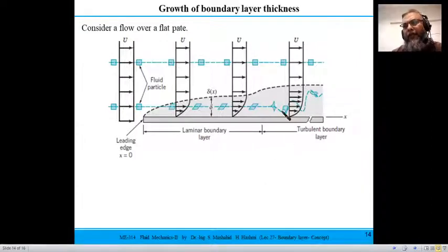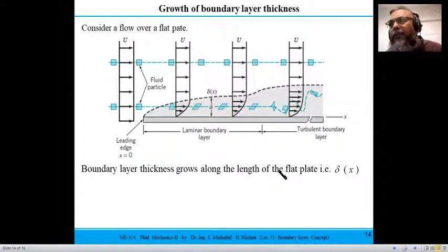And then there is a transition, and then the flow becomes turbulent. So velocity changes take place inside the boundary layer, and in the region outside the boundary layer, no velocity changes take place. So the fluid particle is experiencing no distortion. That would be the region where the potential flow theory is applicable. The region in which velocity gradients are present would be called the boundary layer region, and the potential flow theory is not applicable in that region. This is what Prandtl has suggested.